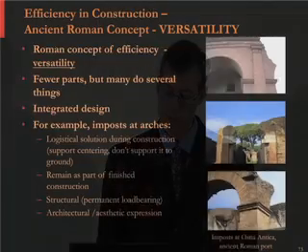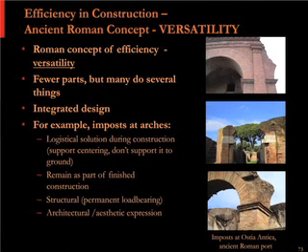So rather than build a wall, build another wall, and then fill the middle with concrete, what they did was this concrete was kind of the consistency of peanut butter rather than the consistency of sour cream like we would make it today. So this was kind of a mound, and then they would drive brick wedges into it. So a lot of the tips are broken off, but if you look closely at those edge bricks, you can see that they're all triangles. So those were actually triangular shapes that were driven into a very thick peanut butter-like concrete.